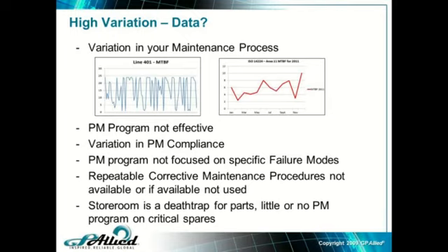Variation in PM compliance. Hey guys, so 30-day PM, you got all month to get it done. Just get all these PMs completed so we take care of our PM compliance. Boy, this is a big mistake. Big mistake. And the PM program not focused on specific failure modes. Failure modes is how equipment fails. That's what we want to look at with our preventive and PDM program. Specific failure modes and their causes.